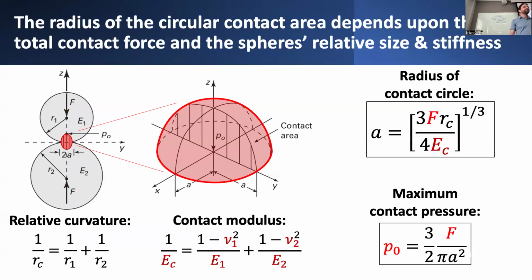We can do some other things to then also figure out what is the apparent radius of this contact circular area. It requires basically just applying some formulas and accounting for the fact that that radius or area of contact will depend partly on how elastic these two bodies are. Their relative elasticity influences how much they'll deform relative to one another. We can also determine the expression for the relative area of contact depending on how big these two spheres are. Obviously, the bigger they are, then presumably the larger this contact area would become. And we have to weight it in a relative sense depending on how big one is to another.